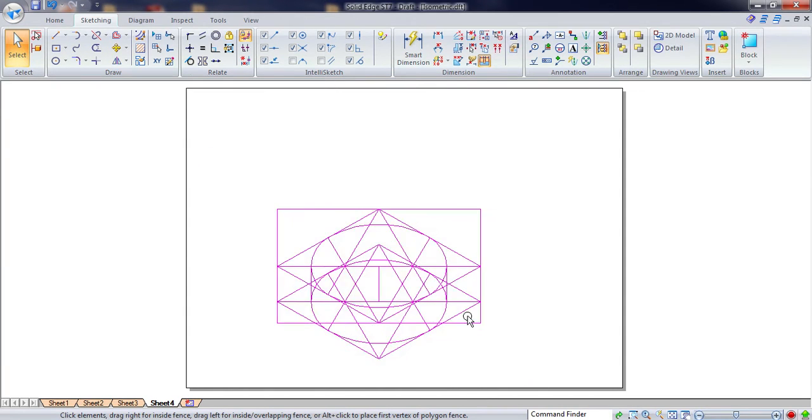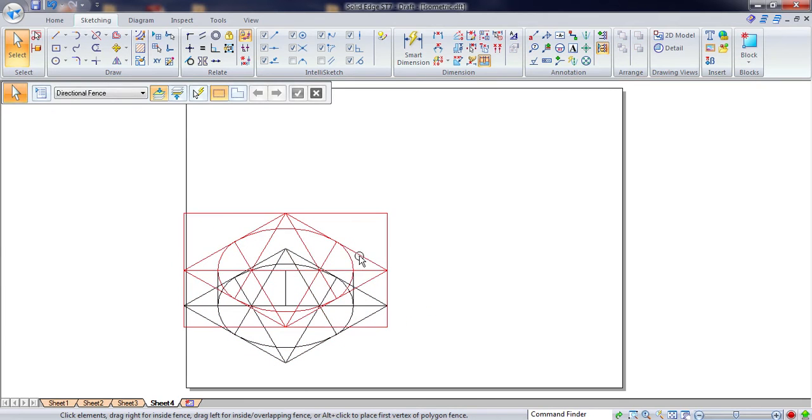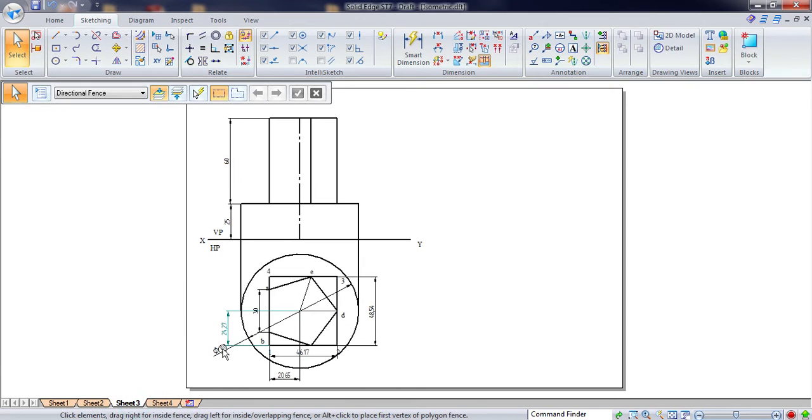Now we'll keep this on one side. Now we have to construct the pentagonal prism. This is a pentagon, and we have put it within a box, and I have named it 1 2 3 4, and the corresponding points I have named A B C D up to E here. First we need to measure the distance from 1 to 2, which comes out as 46.17. We have to place that along the 30-degree line, and the other dimension is 48.54.